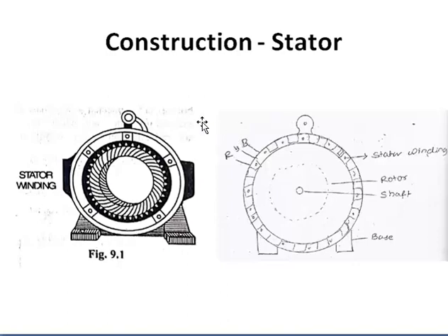Now what we will do is give a supply to the stator winding. When we give a three-phase AC supply to a three-phase winding, it creates a rotating magnetic field. That we are going to prove. For now, just assume that whenever we give three-phase supply to a three-phase winding, it will create an imaginary rotating magnetic field. You can assume a magnetic field here, N and S, which is rotating, and that magnetic field rotates with a speed called the synchronous speed.